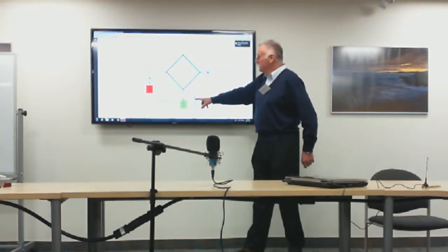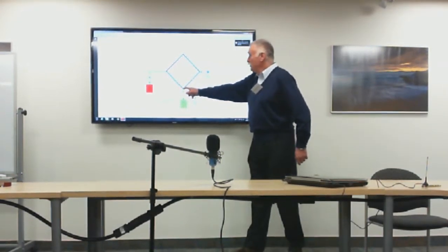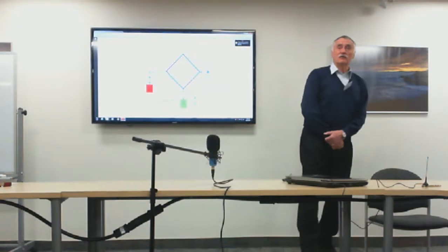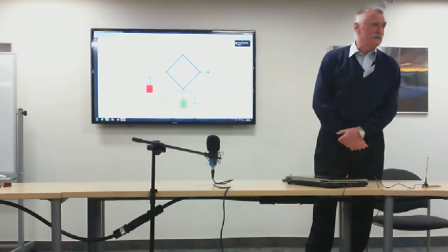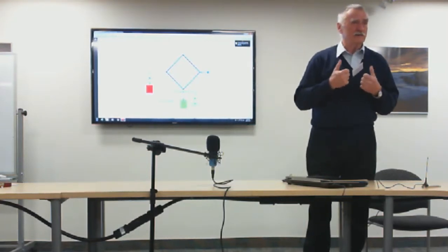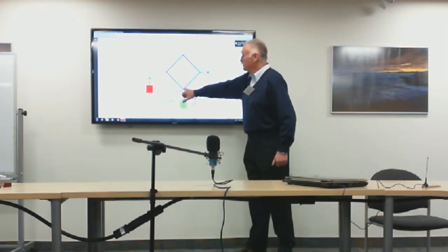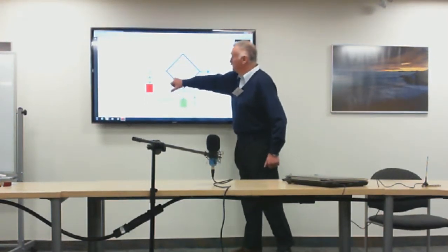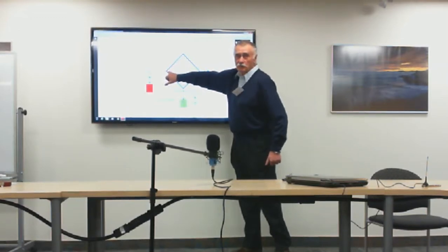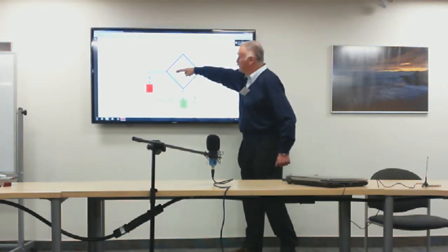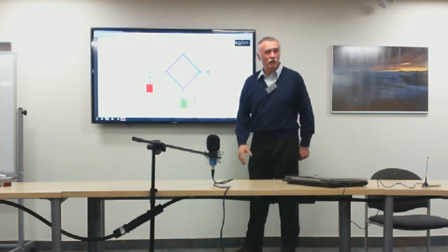Now, because the receive diode is a dead short circuit to the ground, each coax section there is a quarter wavelength section. And you know, a quarter wavelength transmission line short circuited at one end is an open circuit at the other end. This by itself is a test question. So the receive relay shorts this point to the ground. And the next quarter wavelength section here acts as an open circuit. This quarter wavelength section there acts as an open circuit. So the whole entire setup is like if you have a pair of scissors and you cut the bottom half off and you drop it off.